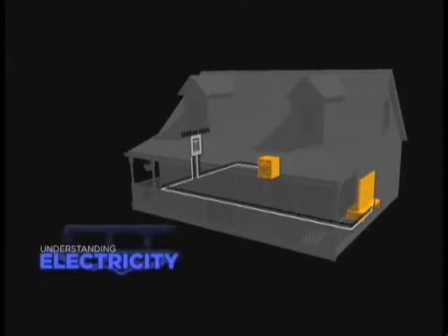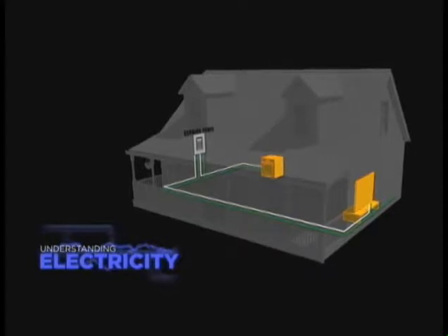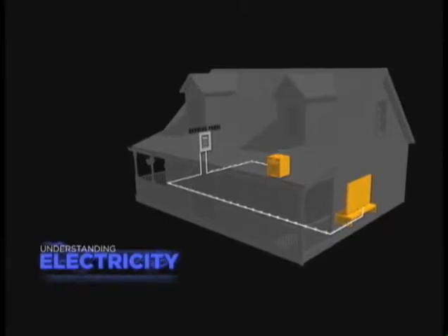Electricity always wants to return to its source to complete a continuous circuit. A typical circuit has two conductors, one that flows from a service panel to an appliance and one that returns the current to the panel. A neutral wire and ground wire are both connected to electrical ground. The neutral wire completes the electric circuit by conducting current away from the plugged-in electrical device. The ground wire is a safety device that carries electric current away from a device when the circuit or plugged-in device malfunctions.